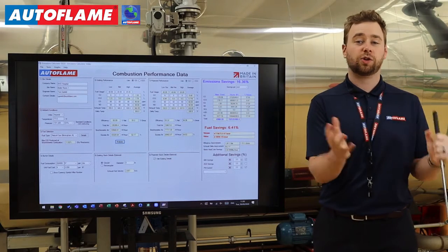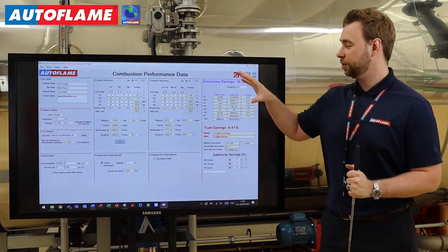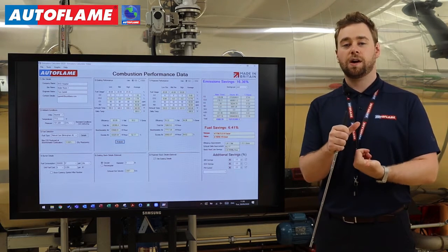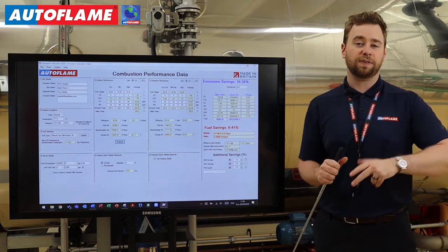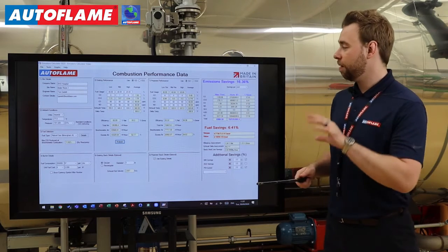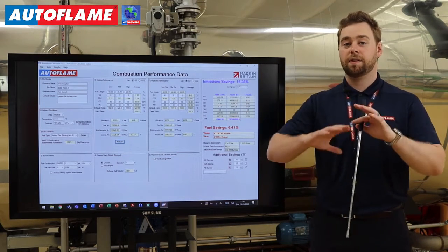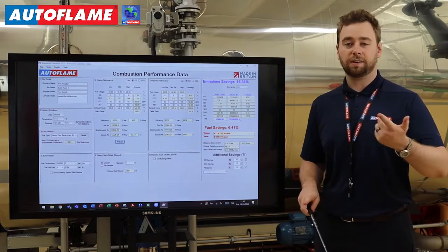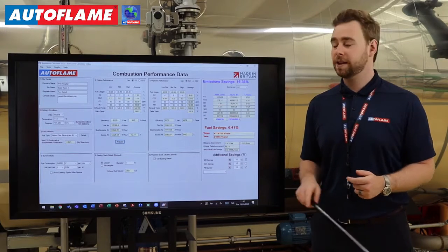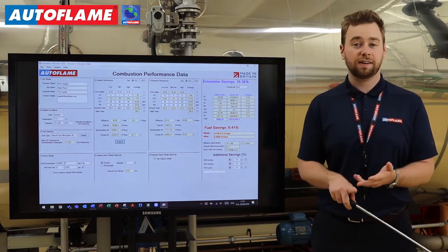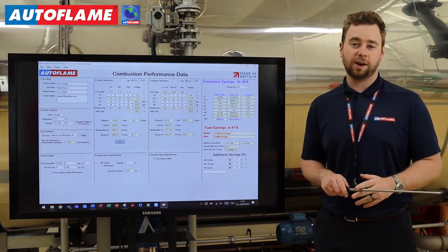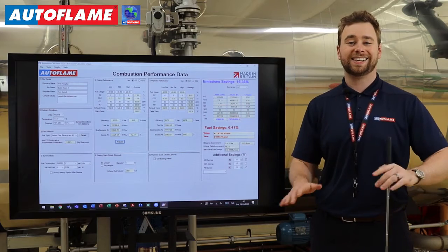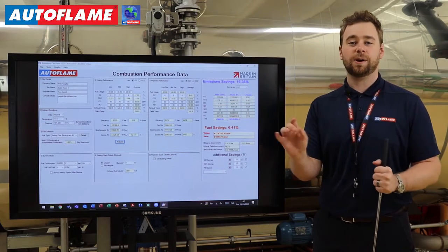So we're going to use historical performance data to input O2, CO and NO values at your high, mid, and low fire positions. Based on this particular burner type, the size, loads of different factors, I know for low fire, I'm going to put in 6% O2. And then for my mid and high fire, I'm putting in 5% O2. Now the CO, across the board, we're dropping to around about 60 ppm, and we're keeping the NO the same at 50 ppm.